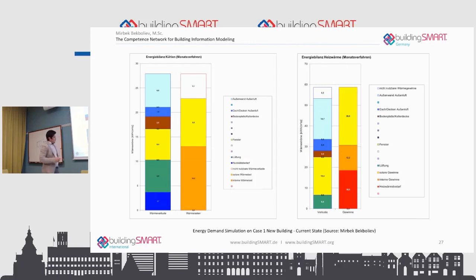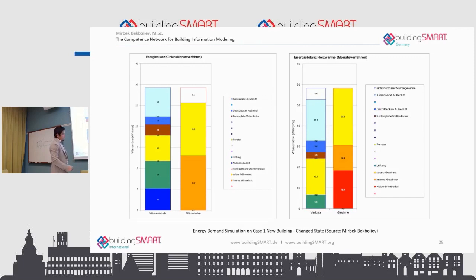Now I want to show you the example. The building, we had the heating load 18.5, right? This is simply a screenshot from the energy simulation as a result, and you have the breakdown here. You see that we have 18.5 kilowatt hours per square meter per annum. I installed a skylight, you remember, and I now have 18.4. So I got some minimal effect, so it doesn't bring so many positive sides.